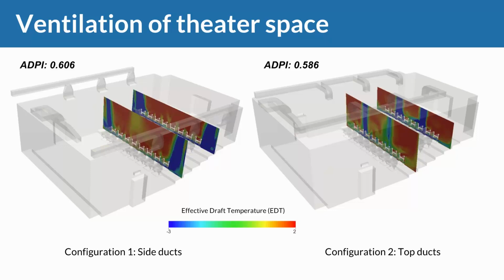Okay, to wrap this up, this was now a convective heat transfer analysis. So the first one was isothermal, right? In the ducting work, in the demo one, we didn't look at thermal effects, we didn't look at buoyancy, these sorts of things. In that analysis, we included convective heat transfer, so it's not isothermal anymore. So we can also visualize temperature fields. And from this information on temperature fields and velocities, we can compute quantities that give us an indication of whether or not occupants will feel comfortable in these rooms.